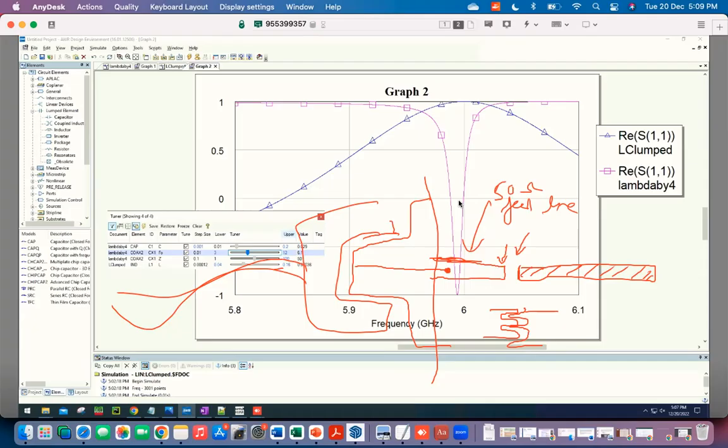In practice, every such joint will have some small amount of reflection happening, but if it is designed properly, then that effect will be very small. The capacitance will also be very small, and if capacitance is small, then reflection will also be small.